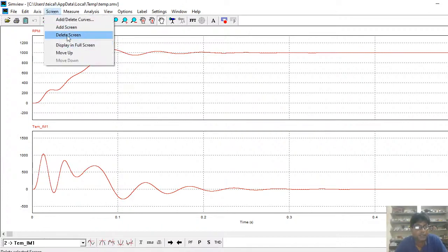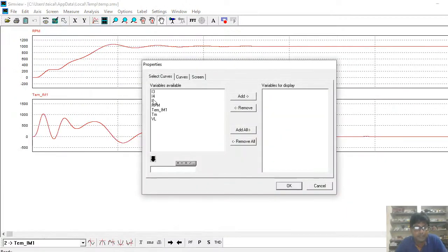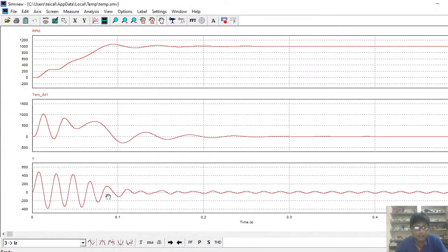And if you want to see the phase current, this is the phase current, as I was telling, the inrush current. Initially it is very high up to 0.1 second, and once the machine has fully accelerated, it comes down to its rated value. It's a no load current. Full load current will be higher. How to calculate the rated torque and all that, I will show you one by one.